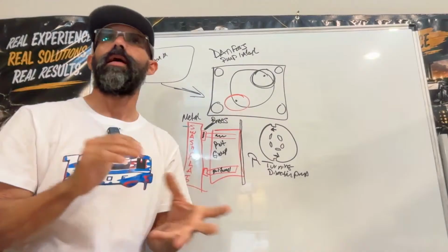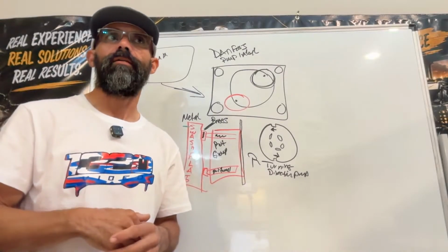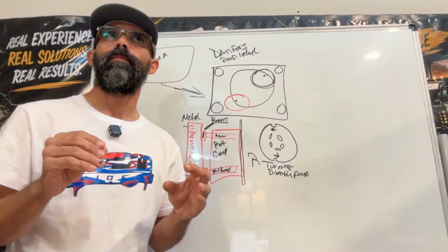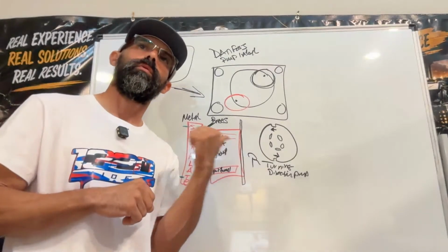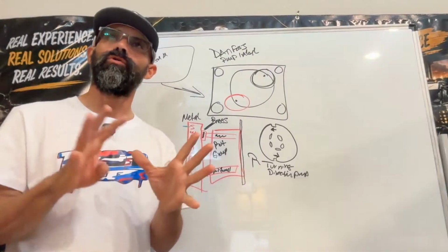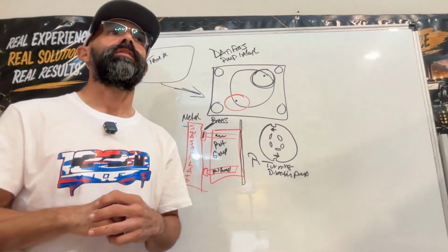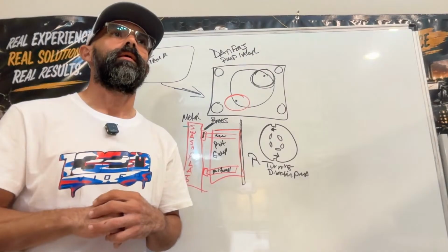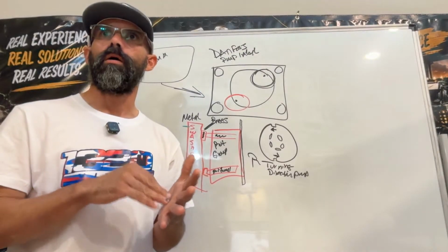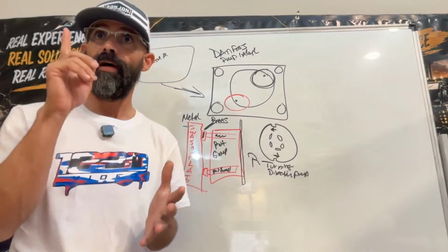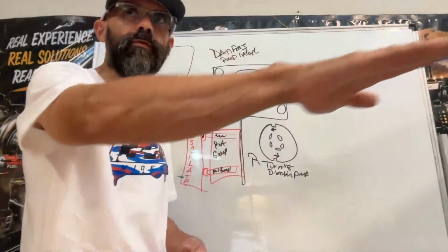I have machine flat surfaces that they use to rebuild these. The closest thing to that is a certified granite block stone. Certified meaning that it's been inspected and is true flat all the way.